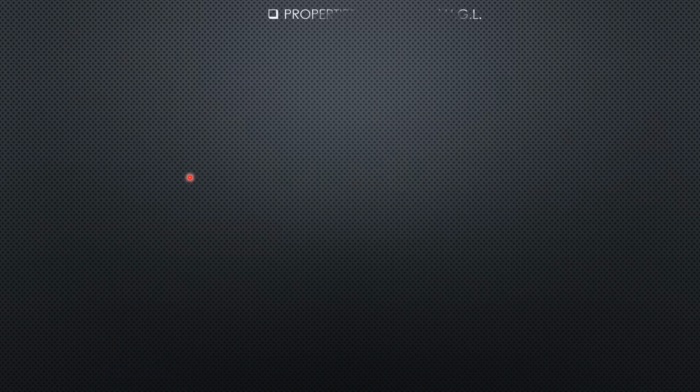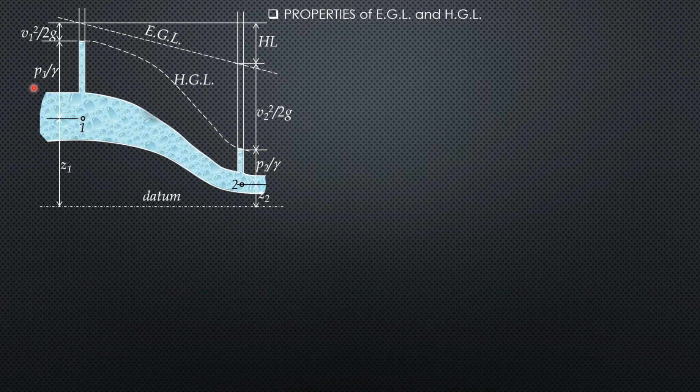So still on the properties of the energy grade line and hydraulic grade line. If this is the system, notice that the energy grade line is always sloping downward in the direction of flow unless there is a machine where it will rise. Then the distance between the energy grade line and the hydraulic grade line is always equal to the velocity head. So here it's v1 squared over 2g, which is small because the section at 1 is bigger, so the velocity is slower.